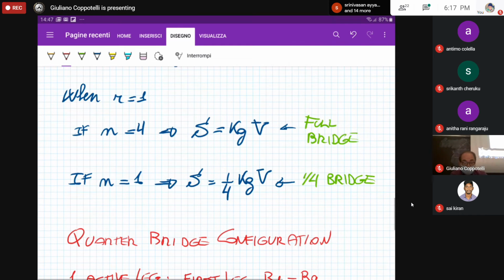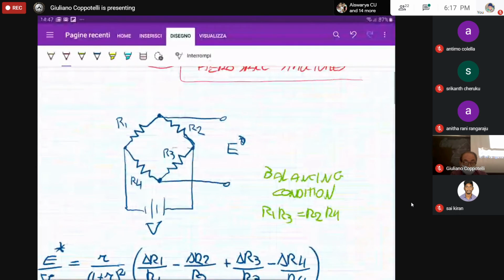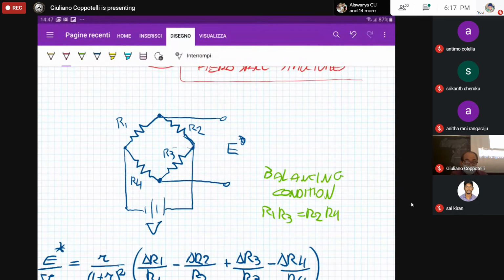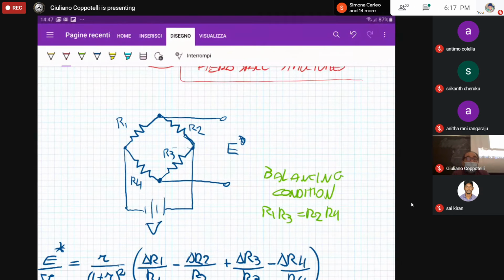Okay, so going back to the general circuit here. We are having R1, the only active leg, and the resistance is equal to the strain gauge resistance Rg. So we still have the bridge itself, but just one strain gauge, that is the R1, in the R1 position.